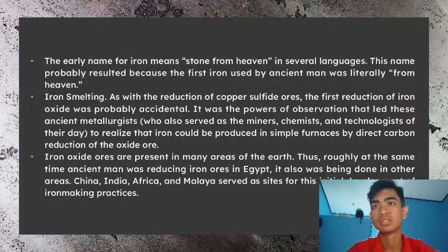The carbon serves two purposes. It must react with oxygen, or burn, to supply the heat necessary for the smelting operation. In this case, the carbon is serving as a fuel. However, the carbon also serves as a reducing agent, reacting to free the iron from the iron oxide, forming carbon dioxide and iron.